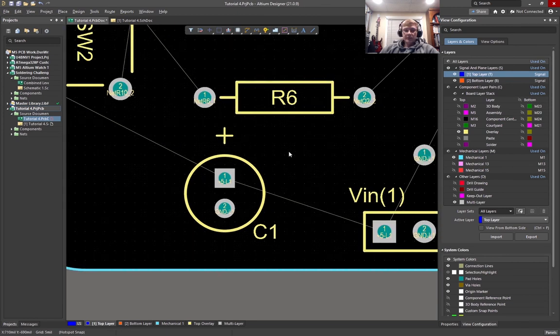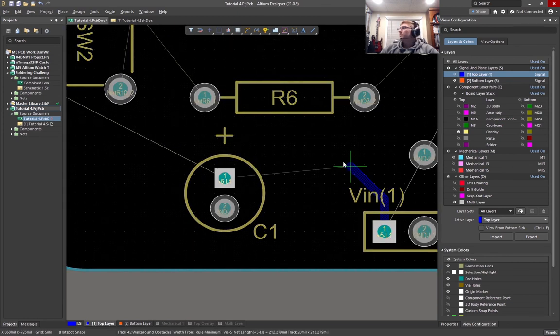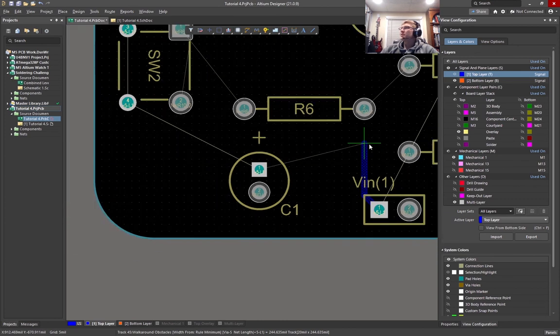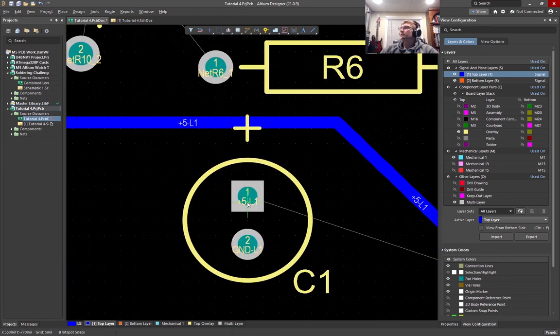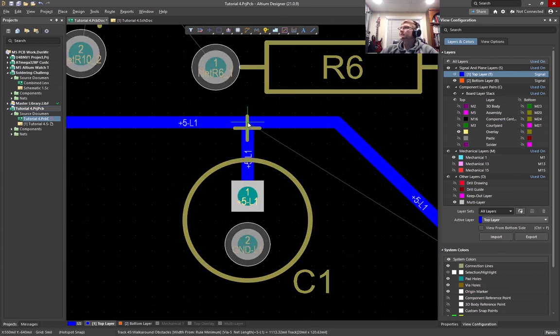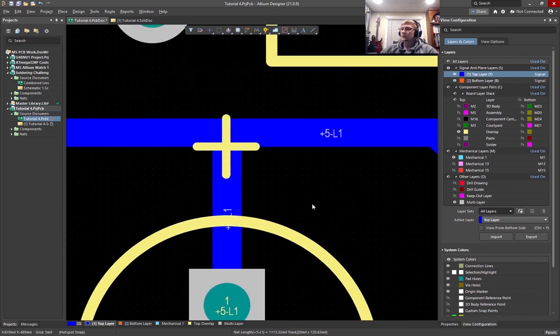One thing I want to do, okay, so there are some different philosophies and different standard practices when you're routing. There's actually a lot of best practices. I recommend doing some research online because there are a lot more things than we can probably mention just in a single video about routing. So I'll give you a couple. One thing is that we try to avoid sharp corners and turns. So we try to avoid 90-degree bends. Here's an example of one of those, something like this. We typically don't want this to stay.